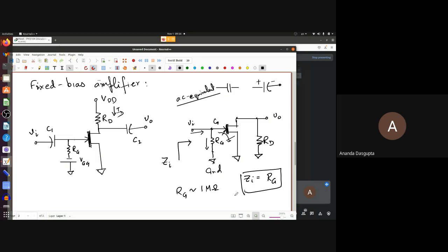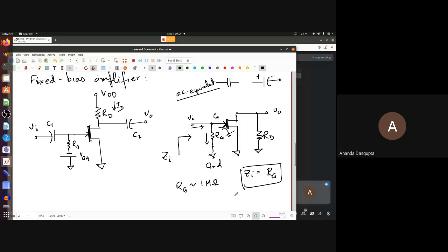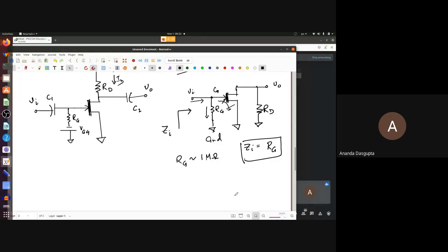Because for a typical input voltage, you will get microampere range current, which is still much, much bigger than the nanoampere range current that you will get between the gate and the channel, and then through that to the source. So we have not even replaced the FET with its equivalent model, and we have still figured out a lot about the circuit. At least we have figured out why RG is necessary. We said that last day, but now we can see it explicitly in the circuit. Also, roughly how large should RG be? Mega ohm is fine.